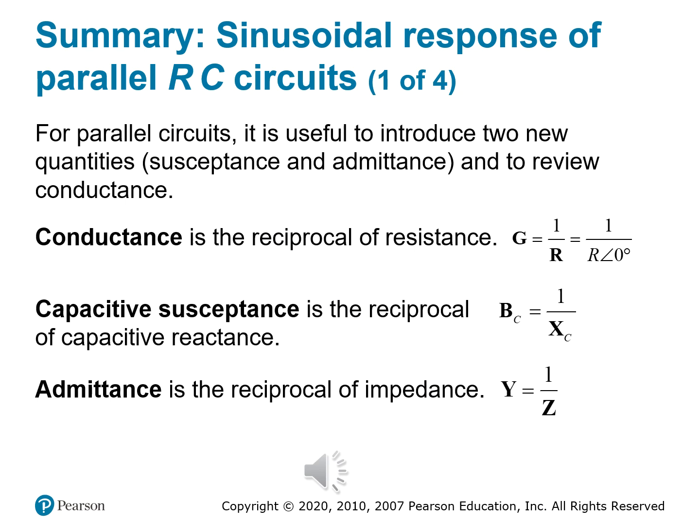In a parallel circuit, admittance becomes your total ease of current flow. So while impedance combines R and X, right? So resistance and reactance, and we do that in a single triangle in series. Admittance does the same thing, but admittance is for the parallel system. The triangle is going to be your new best friend because you're going to have headaches if you try to do it any other way, right?